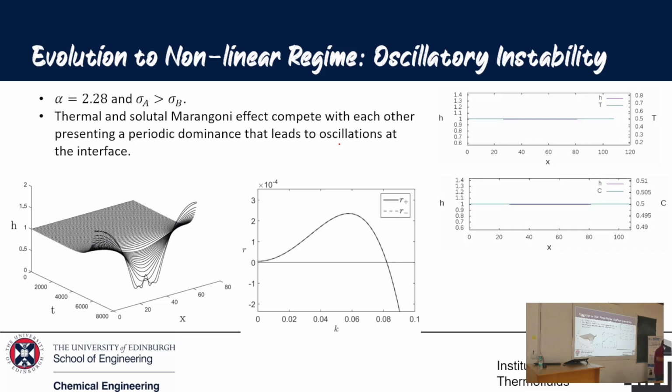And in terms of this oscillatory instability, because thermal Marangoni and concentration Marangoni are in opposite directions, we still have the ratio of thermal Marangoni and concentration Marangoni. So can that ratio somehow govern whether the film will be breaking or not? Yes, it does. You're absolutely right.